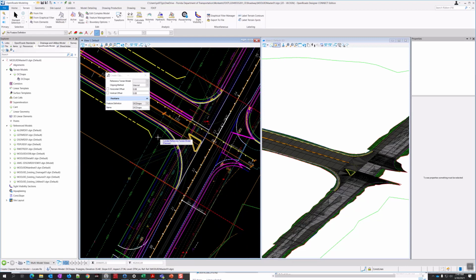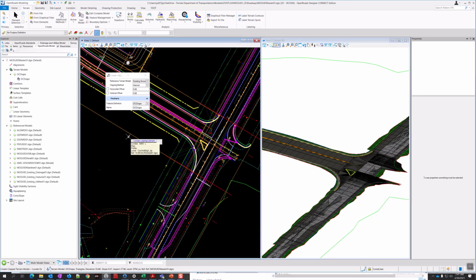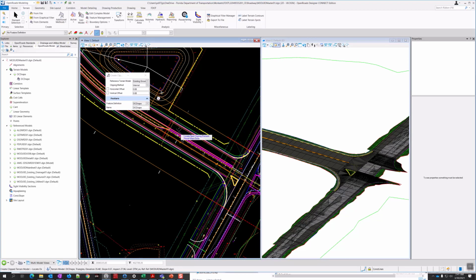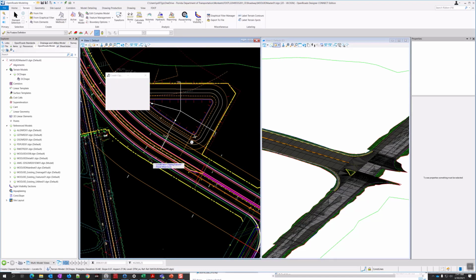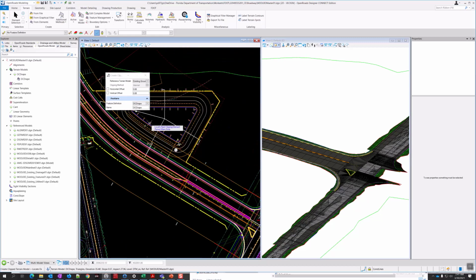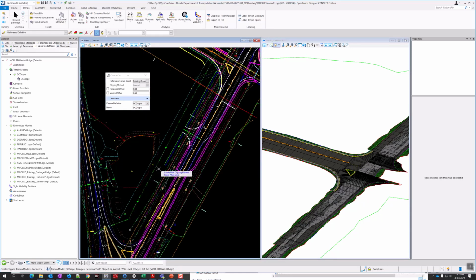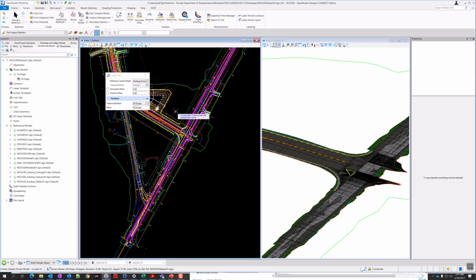Now, once this is located, reference terrain models, so first we need to select this GDTMRD01. So select the boundary, and it wants clipping elements. The clipping elements are going to be all our corridor handles. So I'm going to do this left, right, this main line, which should be 3 there, I'll do the pond and US 98. And then reset when done.